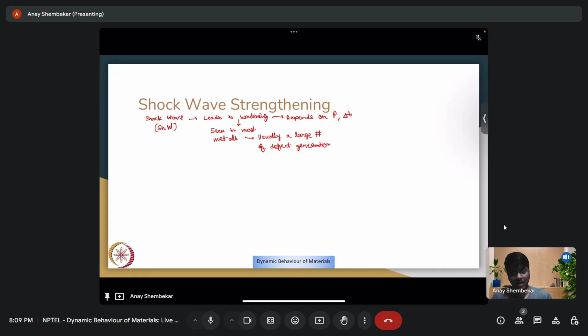So if we see the hardening versus square root of pressure, the plot would look something like this for SS304, something like this for nickel. Another plot we can think of is hardening versus pulse duration. So it increases and then becomes constant, increases and becomes constant.